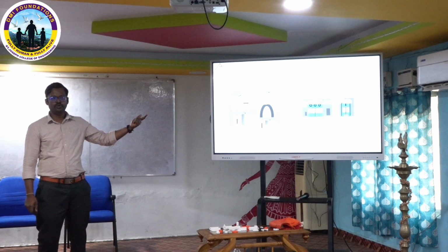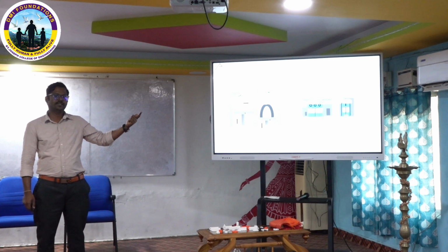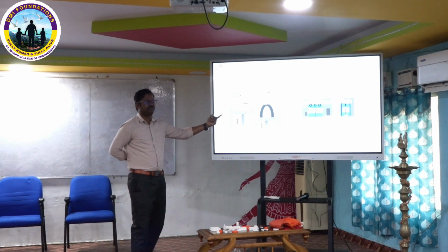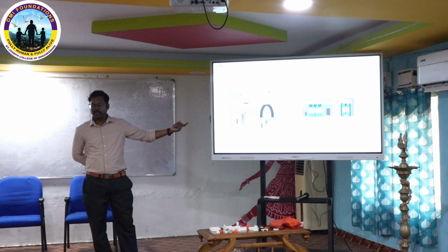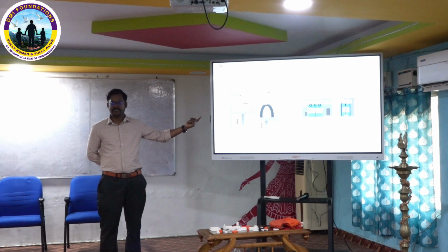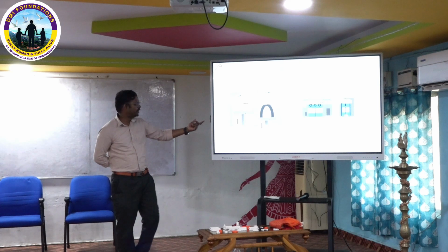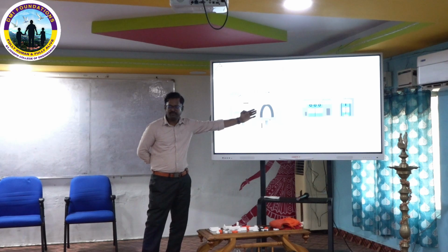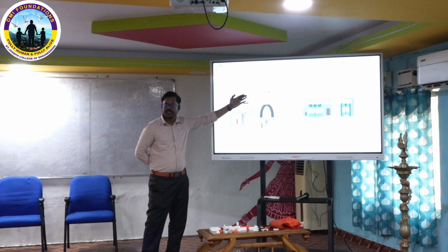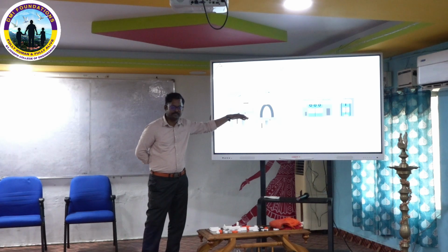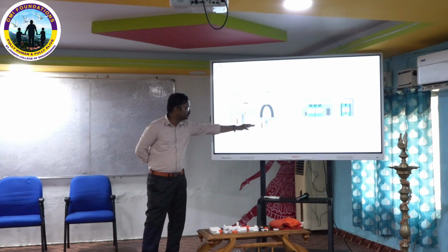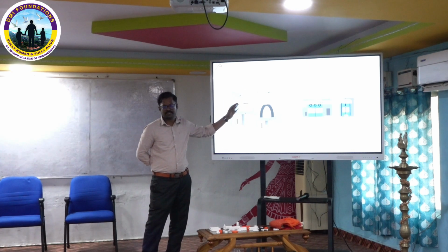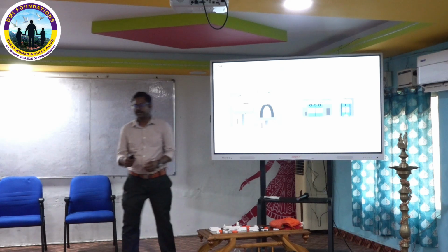Here I show you two different techniques which are powder based only. The first one is the laser powder bed fusion process, which is also called SLS, or DMLS. What is going to happen is, the recoater is going to deposit my material on the build platform. Then the laser sinters the cross section. Then the bed goes down, then the next layer. Like that, the full fabrication process is completed. Then we take it out and clean it.